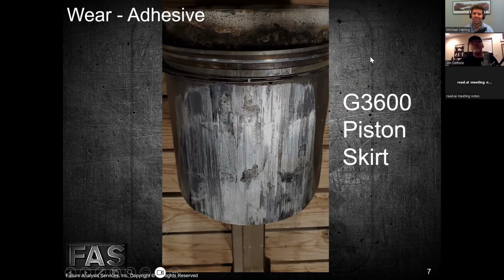And that's something that we teach in our classes as well, as part of our metallurgy module, because you're also familiar with heat treating of parts. So when we see those temper colors and a part has been hardened and tempered, and if it's been tempered at 350 or 375 degrees and we see that it's turned blue, we've effectively hurt the heat treat of that part because we've over tempered or softened it.